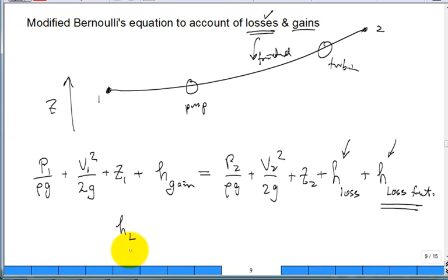All right. Well, how about a friction factor? Length of the pipe divided by the diameter of the pipe times either the velocity pressure, or that velocity head in energy per unit mass, or the velocity head in terms of the elevation head, right? The traditional head. So that would be V squared divided by 2g. And so it depends, we're not changing the diameter. We have one velocity through that long run, okay? How many people are familiar with this equation, seen it?